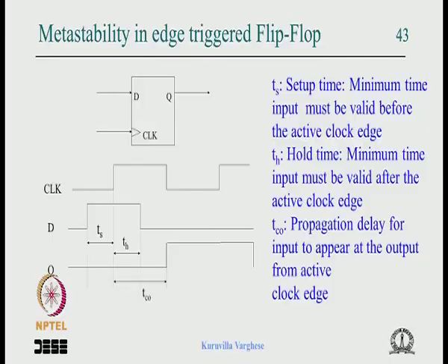So it is a disastrous thing, and many times this issue is not taught in the basic course, but it's a very serious thing, and most of the time the design practices a novice uses don't consider metastability. It's a really bad thing to do, but most of the time, because of reliability, these devices are very fast and the probability of that thing happening is low, we are saved, but this should be kept in mind.